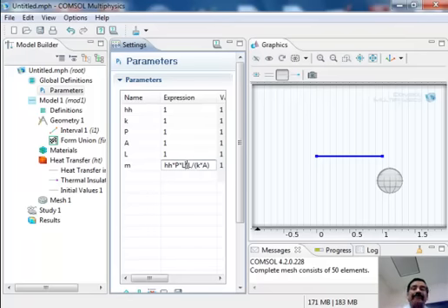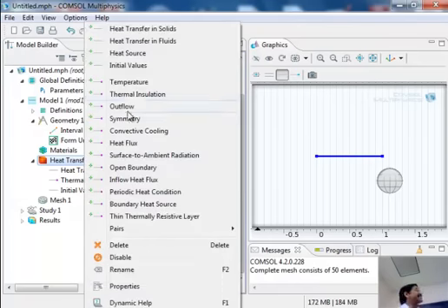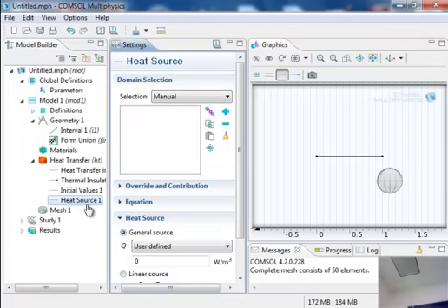Okay. So I have defined so far all the parameters that are appearing in the problem. What else do I need to define? I need to define the source term, the heat, this term in the equation, Q. Right now it is just a symbol Q. So I go and right click on this and say add a thermal source, heat source. Then it adds another folder. So the building process for the model is add as many folders as you need here, defining everything in this equation. So every folder is like writing any line in your Matlab code, if you like.